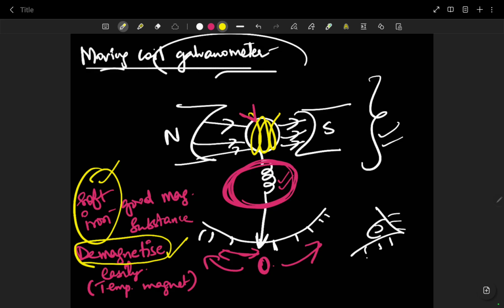So if you see the formula of torque, it would be B I N A sin theta, is what we have discussed, right? So to produce constant torque, if we take theta as 90, it will end up at one value. So we don't have to consider sine anymore. And this is why radial directions are taken, so that it ends up actually making perpendicular angles over here.